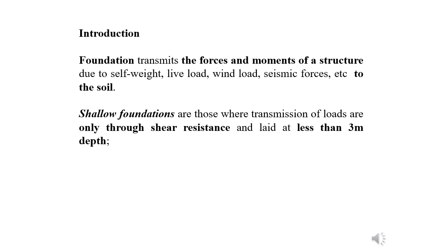You see that a shallow foundation is normally constructed up to 3 meter depth, and it can take the load of the structure based on the bearing capacity of soil. And bearing capacity of soil depends upon the shear strength of the soil, which is available below the base of the footing, right? So it is written there that it works only through the shear resistance, right?